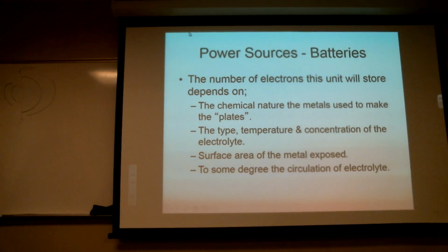One of the areas that we played with, with the lead acid type batteries, is to actually gel the electrolyte. Okay, suspend it in a silica gel. It's still transport, it still works. Okay, but when it gets frozen solid, it doesn't work so well. More badly though, unfortunately with water, when it freezes, unlike all other materials, it expands quite a bit. Water says, all those little hydrogen and oxygen molecules line up, so it actually stretches a little bit.